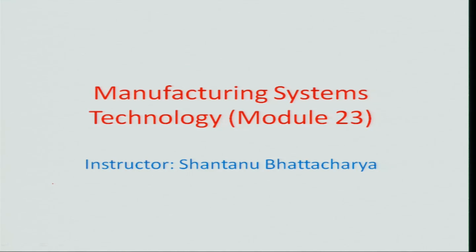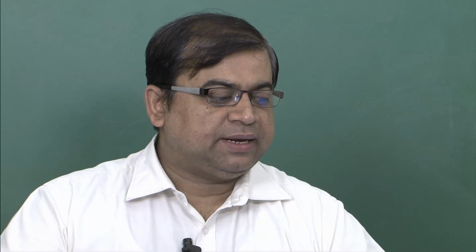A quick recap of what we did in the last lecture. We were talking about the various optimization conditions for optimizing the cutting velocity, and in that sense we had evaluated two different models. One was the optimum cost model and another was the minimum time or the maximum production rate model.